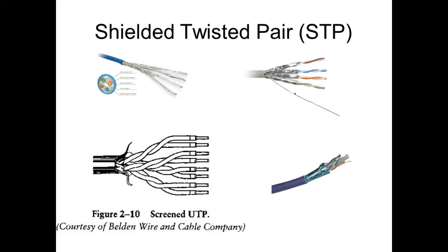Brittany's got my oscilloscope over there on the side, I guess. But if I had an oscilloscope that has a real high impedance on it, and I touch my finger on it, it's going to pick me up. It's going to be 60 cycle, because 60 cycle is being broadcast all through this building. Right? You understand? We have a capacitive effect, so I'm picking up these signals.